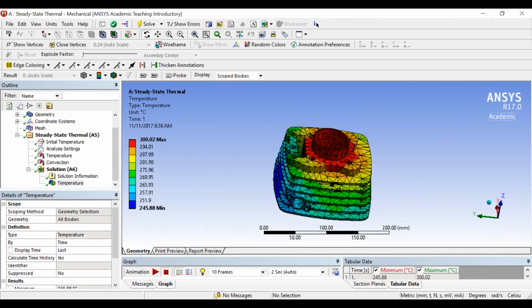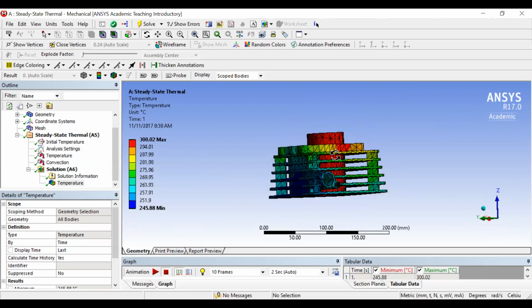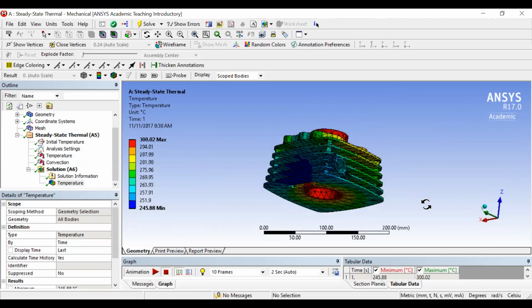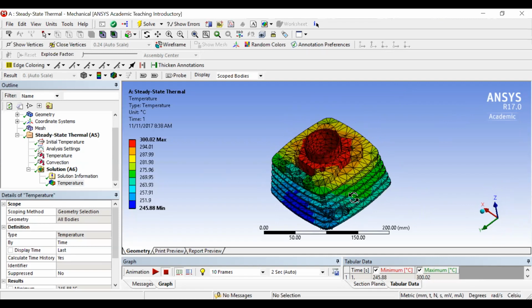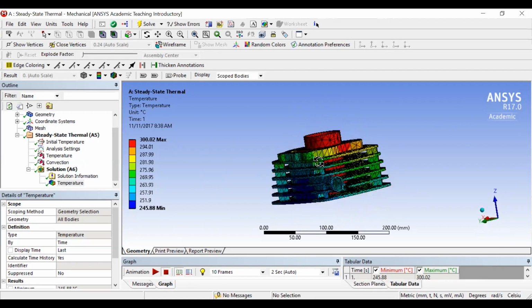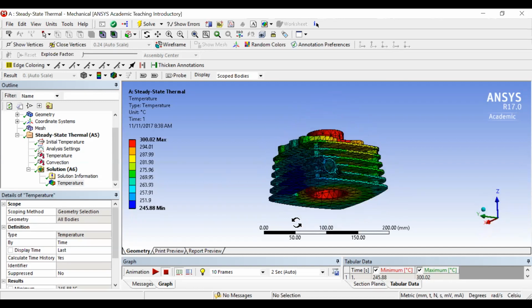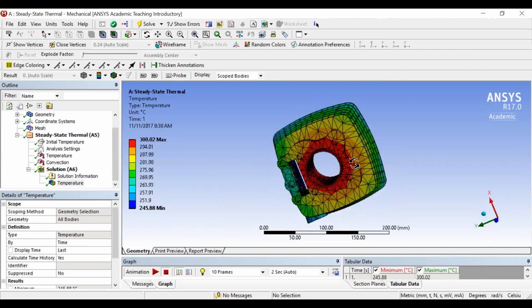That way you can help yourself understand the effectiveness of all these steps. Okay, one thing, when you look at this cylinder block in terms of a design problem, the design actually looks pretty good. The reason is that you don't see any sharp corners down here; they have made good use of the fillet structure.